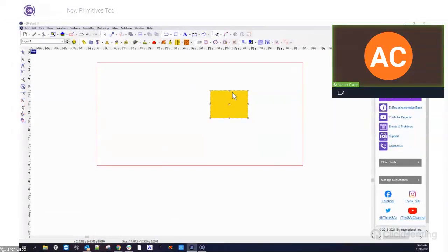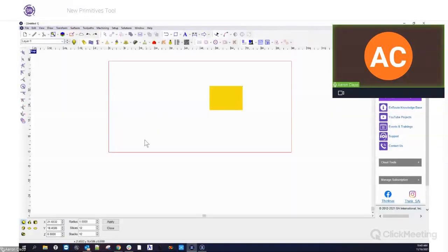So what is the height and width of this? I don't want to go over it. So it's 12 by 17. All right, so now we're going to go to Mesh Tools, create primitive, and let's do a cylinder. Let's increase the resolution here to 250 by 250.